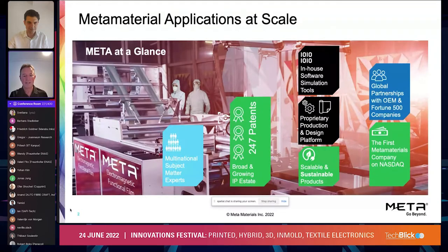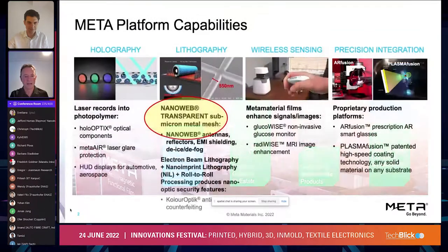In certain cases, we use a phase shift masks approach to actually pattern them. And in others, we use a new type of cast plasmonic printing, all allowing for the creation of structures with feature sizes down to about 50 nanometers.